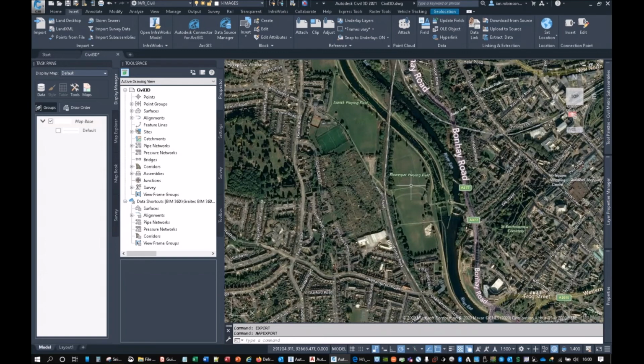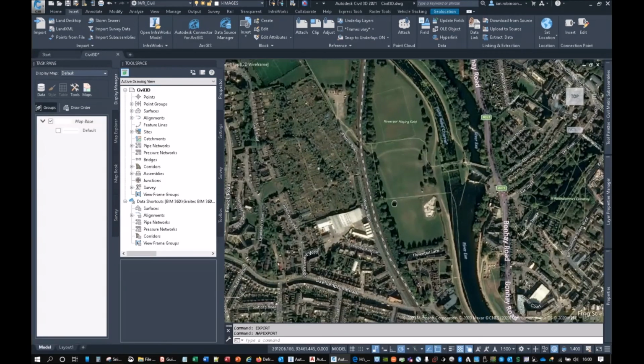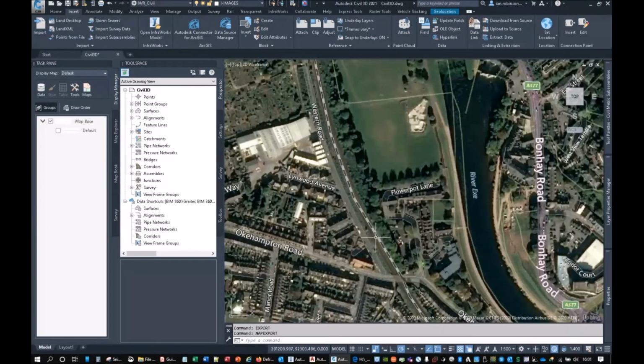So in here, let's say I am going to work in here, and I would like to know what a 1 in 1,000 year flood event looks like. Okay, what is that going to look like on here? Because if I'm going to build on here, I'm going to drain into this road. Am I overloading it before I start? Well, we can use web mapping services. I'll just show you that guide.